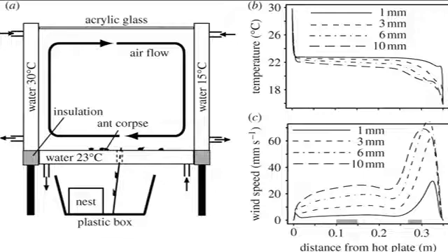A laminar flow cabinet equipped with a state-of-the-art filtration system can reduce airborne contamination levels greatly within the working area, depending on the filtration system of choice. However, the most common application of the laminar flow cabinet is to provide an individual clean air environment for small items not requiring a full-size clean room.